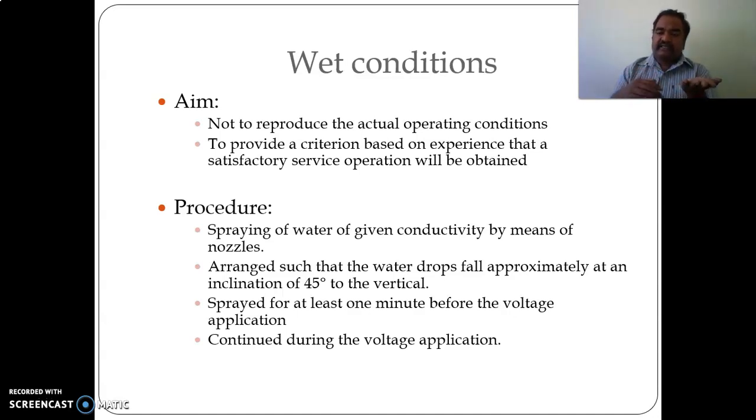You take the insulator specimen and the water will be sprayed onto the insulator at 45 degrees angle from the vertical. And this spraying of water will be started 1 minute prior to the application of voltage, at least 1 minute. And this spraying of water will be continued onto this insulator during your application of voltage. So the same has been mentioned there.